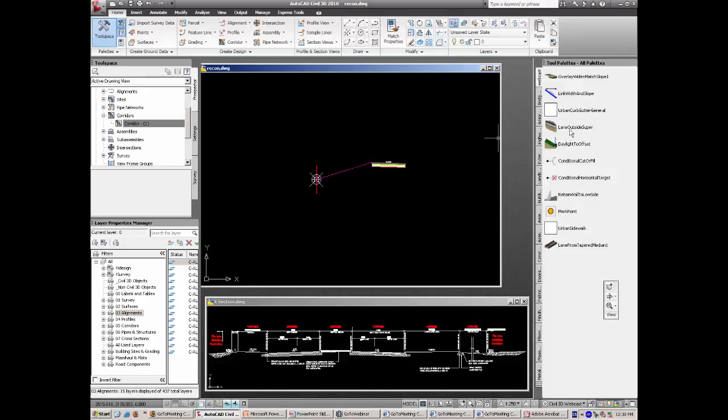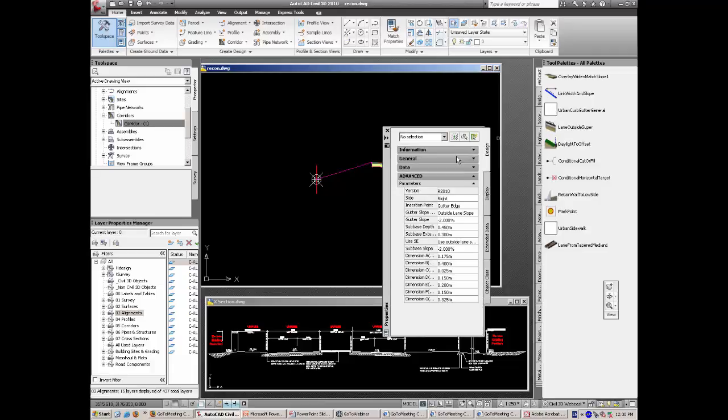We then go and build a curb and gutter. So we've got curb and gutter here. There's a few tricks to this one. So this is actually on the left-hand side because we're working back across from the left, and we're going to attach it via the gutter edge. And I put that in here as well. Now, I'm not paying too much attention to my values for subgrade and everything like that. That's just something you can work on in your own time, I suppose.